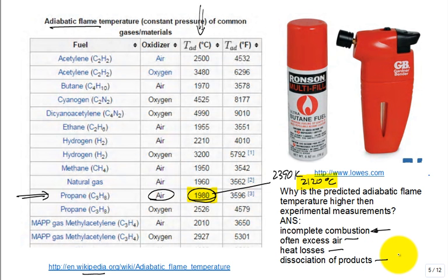When you start to really get high temperatures, it doesn't just like to stay as CO2. Even though it may have completely combusted, it may want to dissociate. And maybe the nitrogen in there just doesn't go happily along as nitrogen. It likes to kind of go to NOx, which is an oxide of nitrogen. And that's that brown haze you're going to see out there. Summer days, you get inverted temperatures and automobiles put out NOx. It reacts at the ground level, and you get haze in the summer in cities like San Antonio and Houston and Dallas.